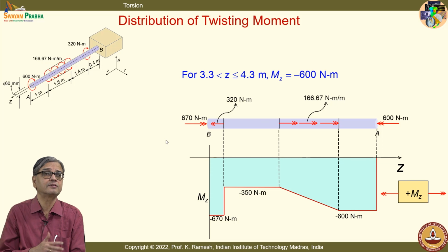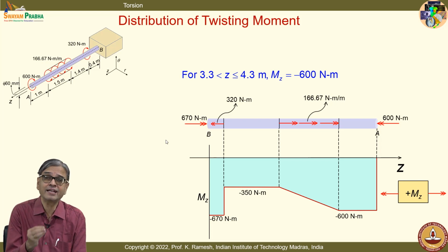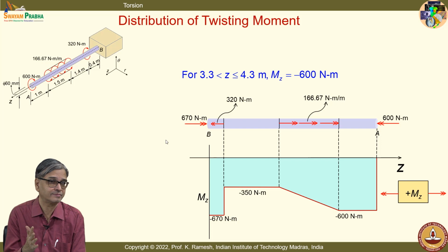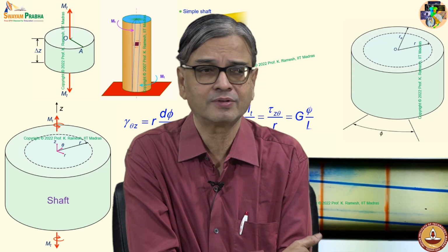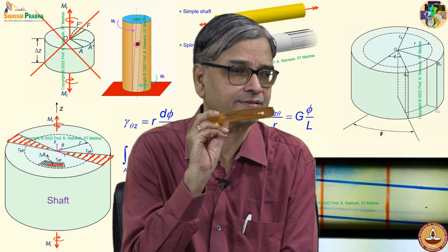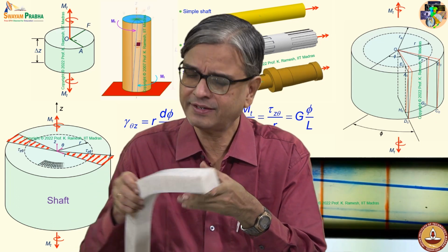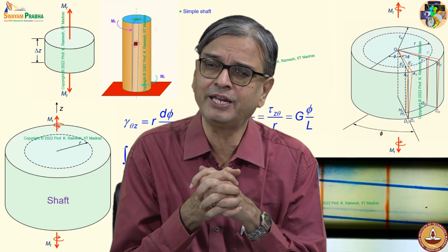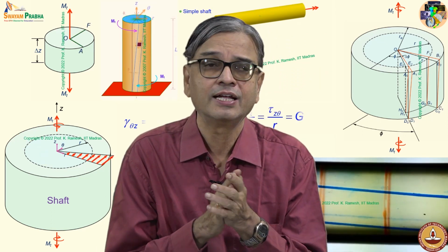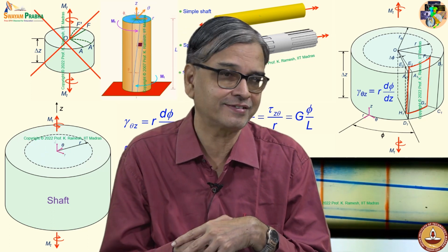Why do you do this? The bending moment or shear force or twisting moment diagram, when you have to design, you design for the maximum load, so that your cross section selected is appropriate to withstand that load. And let me also give you an idea to think. See, when you physically look at it, you are able to see it's a circular cross section, fine. When you physically look at it, you are able to see that this is a square cross section, fine. Can you imagine, you have learnt many quantities in your engineering mechanics also. When you do mathematics, how does the mathematics understand the cross section? Do you have any idea?